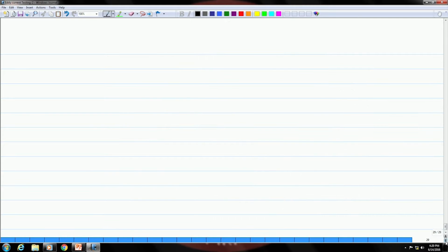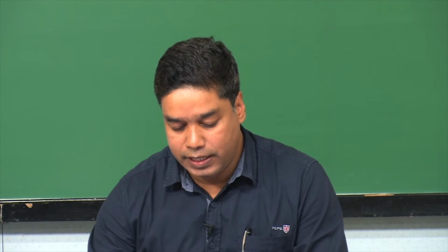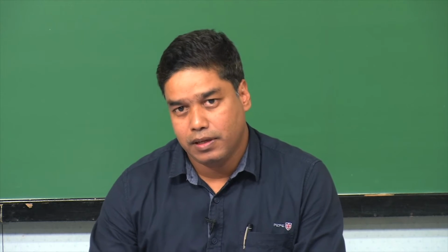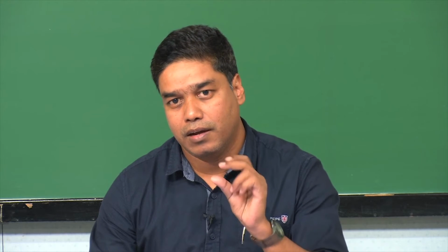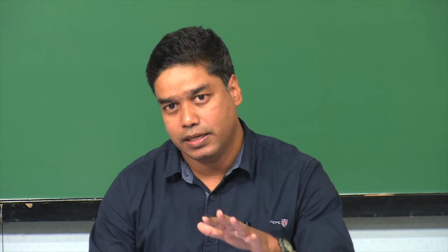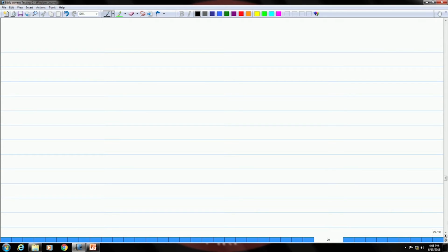Okay. Now, when do you say a depth or a material thickness is thick enough with respect to eddy current, in the sense that at what thickness will you say that beyond that eddy currents will not be able to penetrate. So, the effect of that sample thickness can again be demonstrated with the help of this impedance plane for a given material.